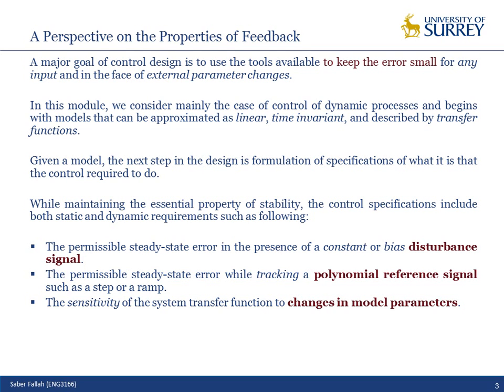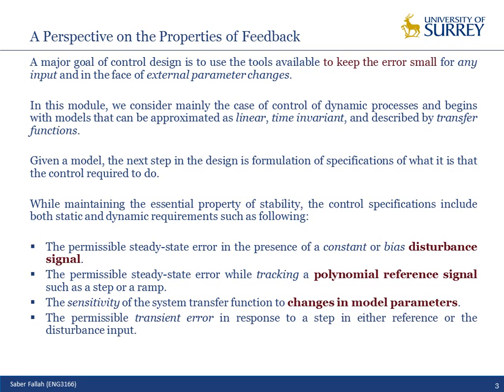Does the system still work with that change of the parameter, or for what percentage of variation of the parameter will the system still work properly? Okay, these are the topics that you need to make sure about when you design a control system. And again, you need to check the transient error of the system, subject to the step input or other types of standard inputs.